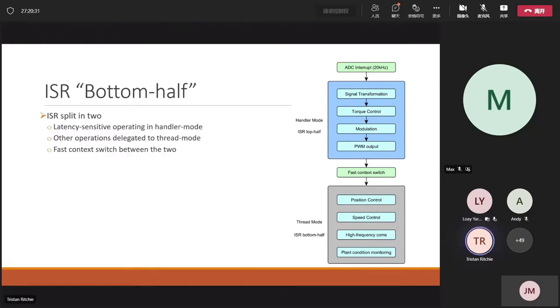Implementing this in RT threads is perhaps a little counterintuitive, as RT-Thread is supposed to be a hard real-time operating system. And by bypassing the scheduler in this way, we've effectively created a soft real-time kernel, as this bottom half ISR thread cannot be preempted by another regular thread.